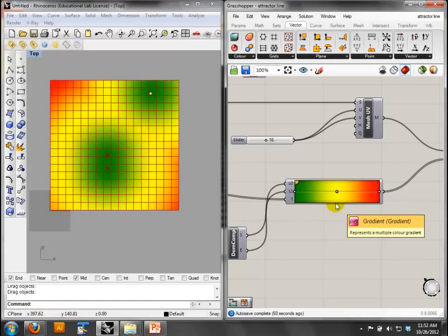Lindsay. That was what I was planning. Yeah, the baking part actually needs a little component, which I'll put online tonight. You need a special component because, in order to get the color to go to the right place, it makes a material for every single mesh and figures out how to apply them for you. You can't just bake this; it'll just be gray. You have to use the bake component that I give you.